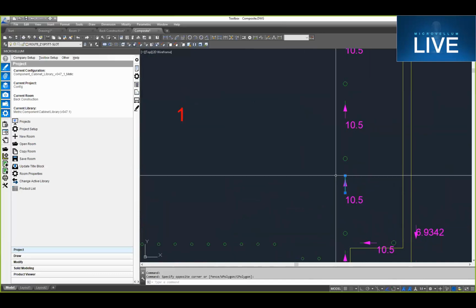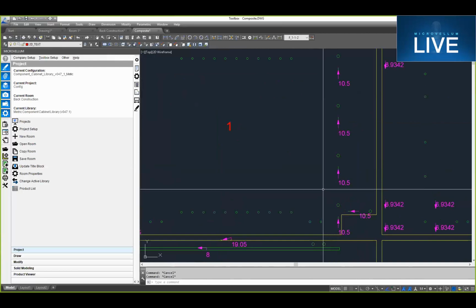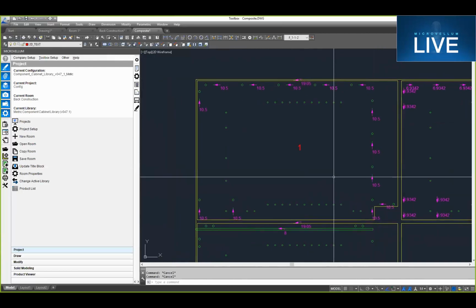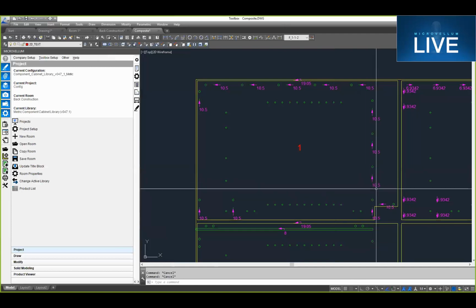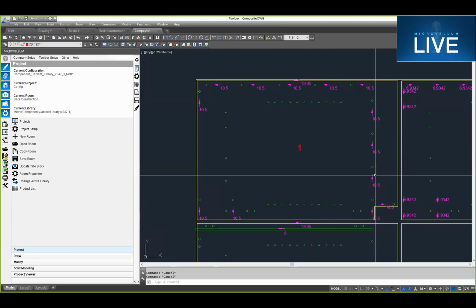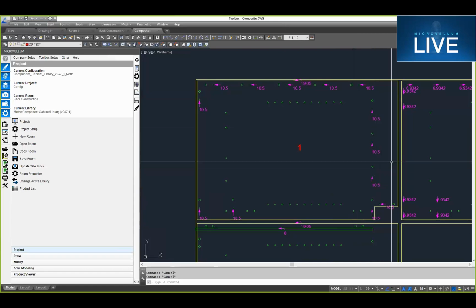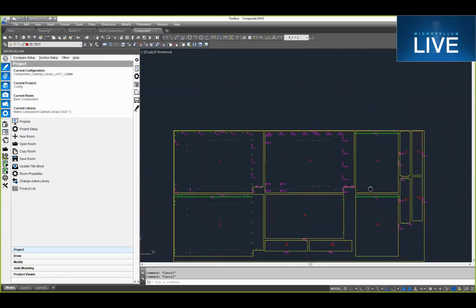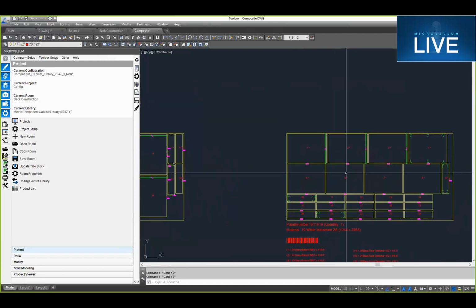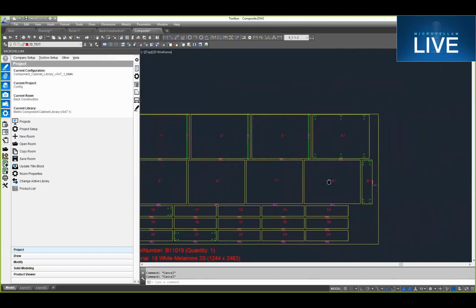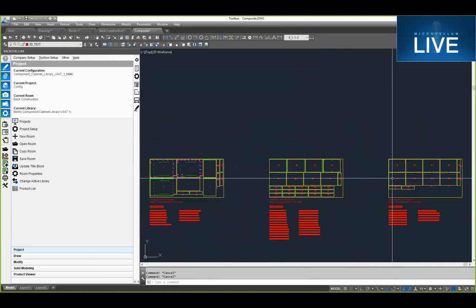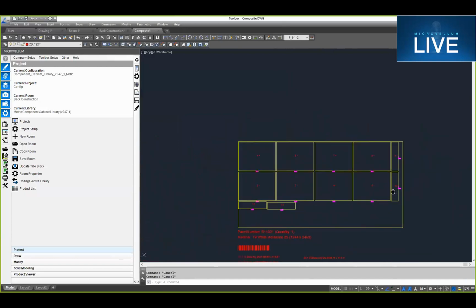Here you can see we've got, this is our fasten link machining. And so the way that this machining works is that there's a T-slot cutter that goes in and machines a groove to receive the fasten link connector. And then you snap those parts together. And so here you can see the machining that's happening 10.5 mil deep. It's coming in, plunging, or ramping in with that tool and cutting that T-slot in order to receive the fasten link machining there, and similar for the Dado construction. That's going to come through in there as well. I've got my cam construction there with my back grooves for those different parts.